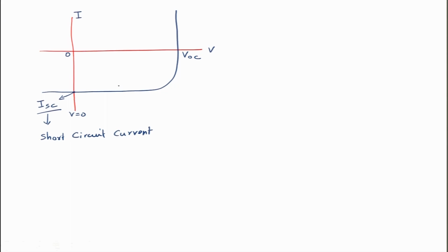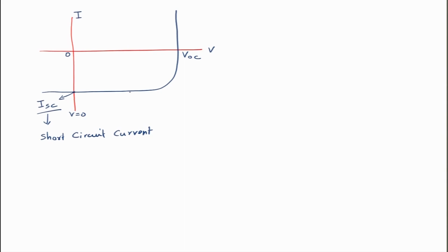Now this depends upon the type of solar cell that you have, material quality that you have, what kind of recombination you have. So for a perfect solar cell which does not have high level of recombination, which does not have high level of SCR current or other kind of currents, the ISC stays flat up to quite a bit of voltage, and before it suddenly starts increasing. So, for a dark solar cell you should obtain characteristics like these, and this shifts to fourth quadrant when the solar cell is under illumination. So, this would be under dark and this is under illumination.